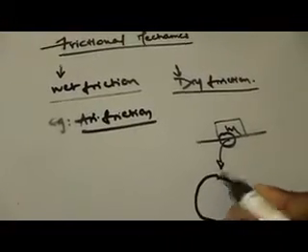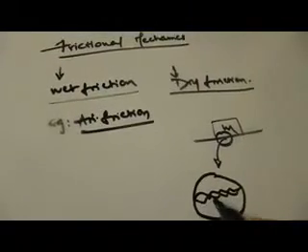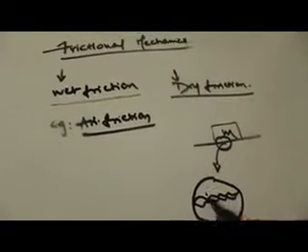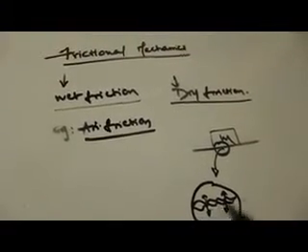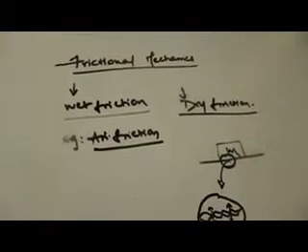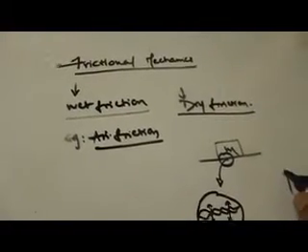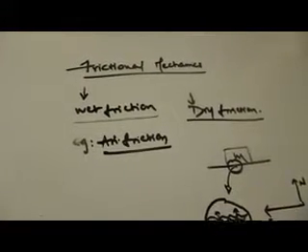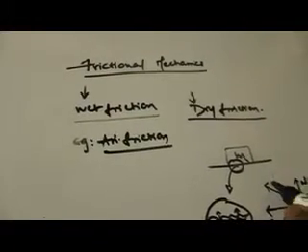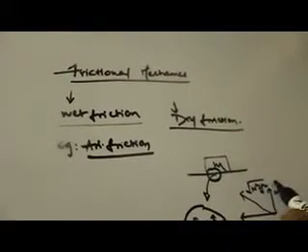This is the surface, the upper surface and the lower surface. Now you can observe the irregularities in contact, and the contact force looks like this, perpendicular to the surface in contact. Due to irregularities, it has two components: one is normal and the other is horizontal. The normal component is called the normal reaction, whereas the horizontal component we generally call friction. The resultant of both forces, given by the square root of N squared plus F squared, is generally called the contact force, CF.